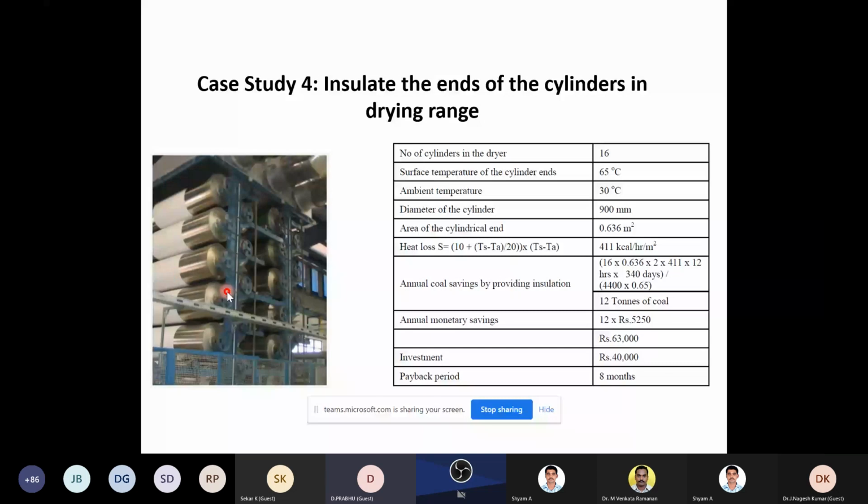Now, steam is going into the cylinders, heating up the cylinder, and this hot cylinder will dry up this cloth. Now, you can see this radiation from the sides, and from the cylinder sides, this is consistent. So now what we need to ask is whether we can feed two sets of fabric, one set of fabric here, one set of fabric here. So you can increase the production as well as minimize the heat loss from this cylinder.